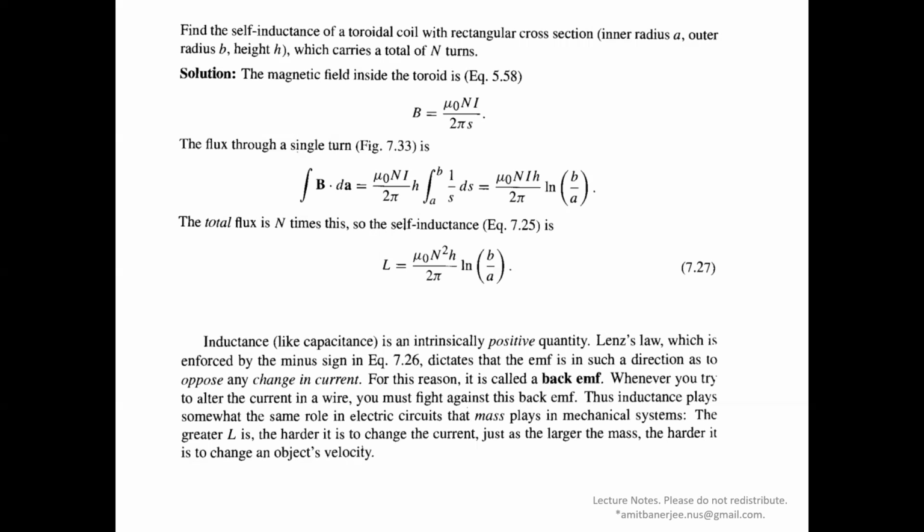Now, an important aspect is that inductance, like capacitance, is an intrinsically positive quantity. Lenz's law, which is enforced by the minus sign, dictates that the EMF is in such a direction as to oppose any change in current. For this reason, it is called a back EMF.